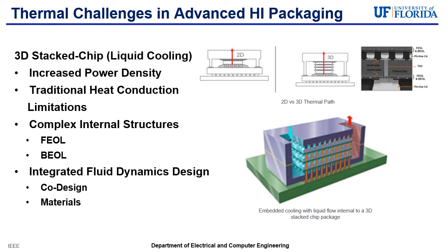The complexity of these internal structures with their intricate FEOL and BEOL layers makes thermal management more challenging. The heat needs to be conducted through these multiple layers efficiently to prevent overheating, which can cause the device to fail. To combat this, integrated fluid dynamics design comes into play, utilizing liquid cooling methods embedded within the chip package. This co-design approach assures that both the materials and the cooling systems work together effectively to manage heat by spreading out and away from the chip.